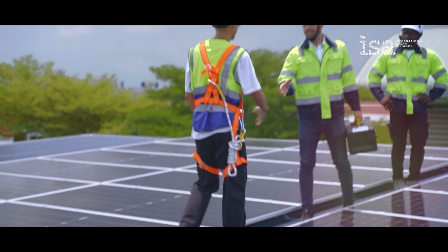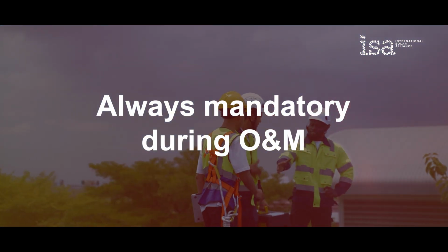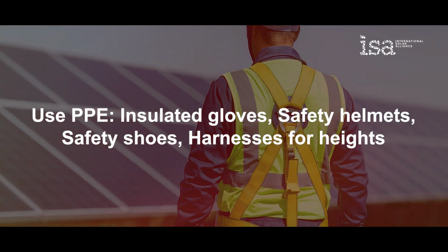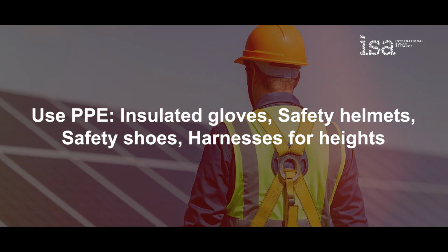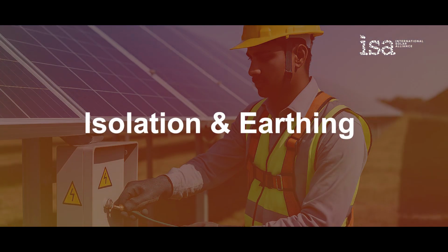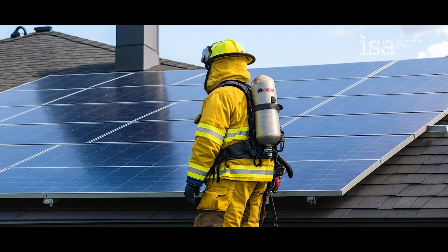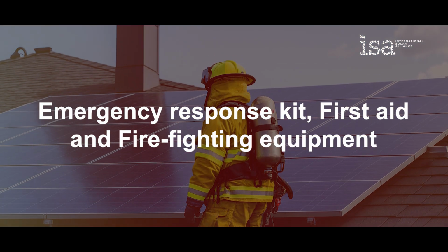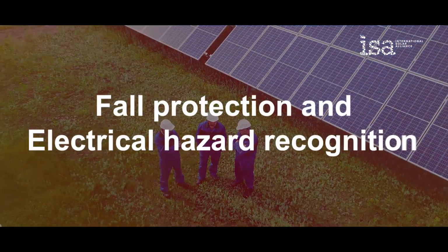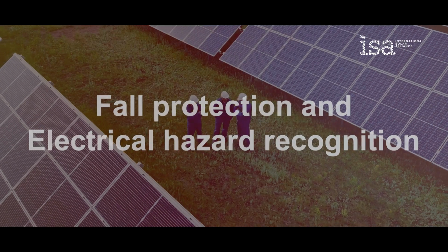Safety protects personnel and assets, always mandatory during O&M. Use PPE: insulated gloves, safety helmets, safety shoes, harnesses for heights. Apply lockout/tagout before electrical work. Ensure isolation and earthing before maintenance on live systems. Maintain emergency response kit, first aid and firefighting equipment. Train staff on fall protection and electrical hazard recognition.